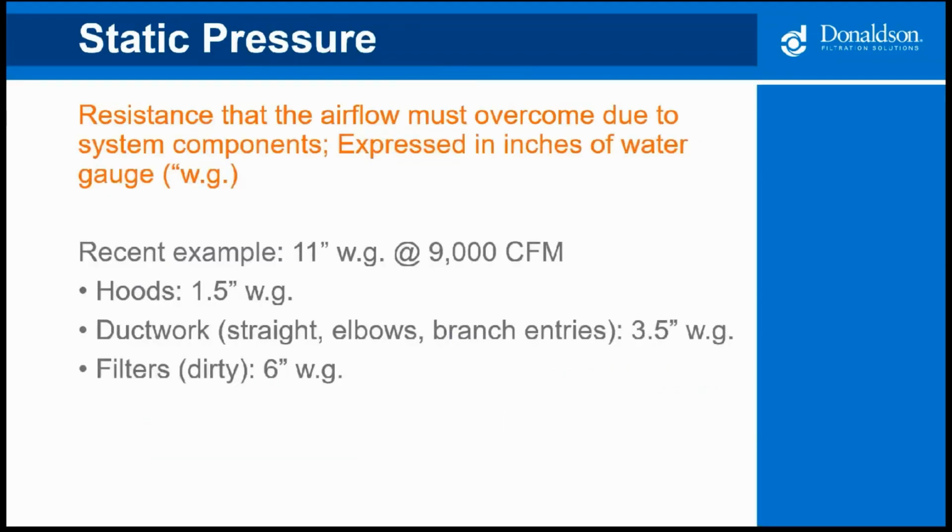A critical component of fan design is static pressure. It's basically the resistance that the airflow must overcome due to system components. It's expressed in inches of water gauge. When we design a system, we calculate the total static pressure so that we can size the fan appropriately.